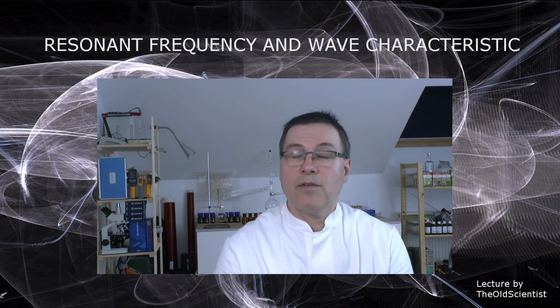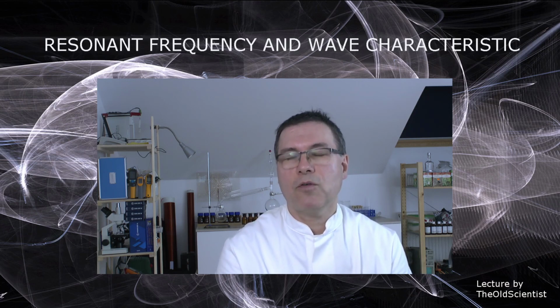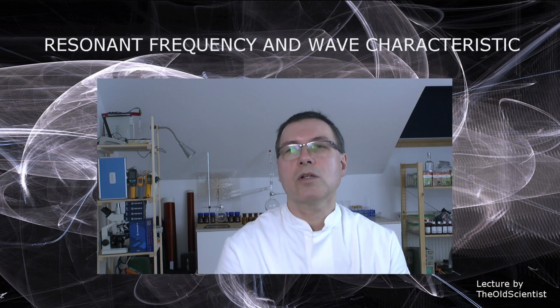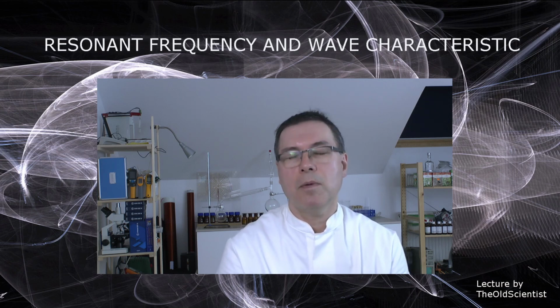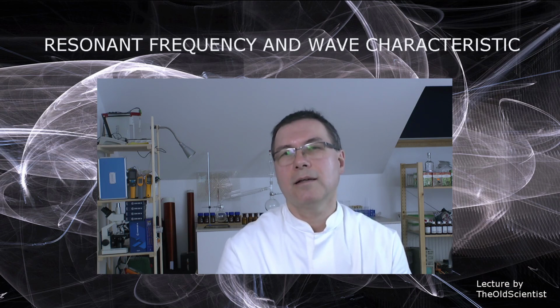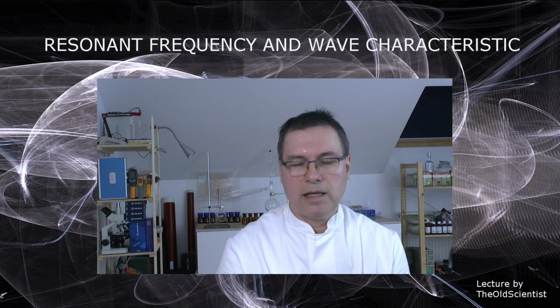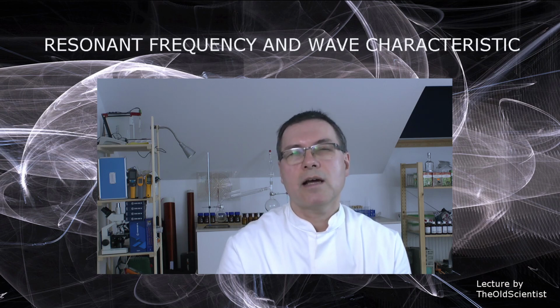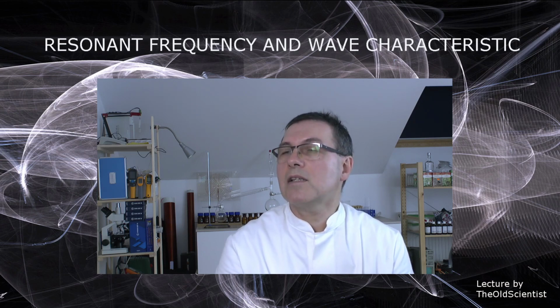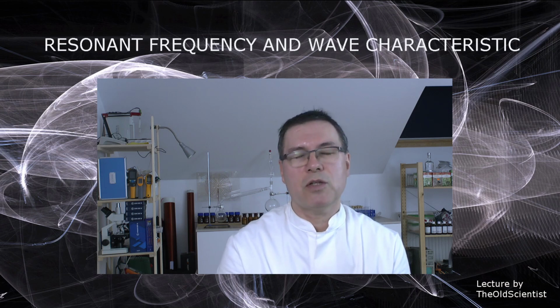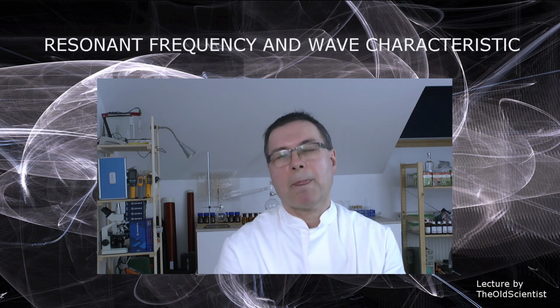However, this is a very, very expensive material, but for high power applications with low losses, Metglas is the only material because it's a fluid metal, if you want. It's glass. Because of that, it has no crystal structure, and therefore it does not have these losses of heating and so on as a normal crystal structure has. So to answer this question, it depends really on the core material. It depends on the strength.